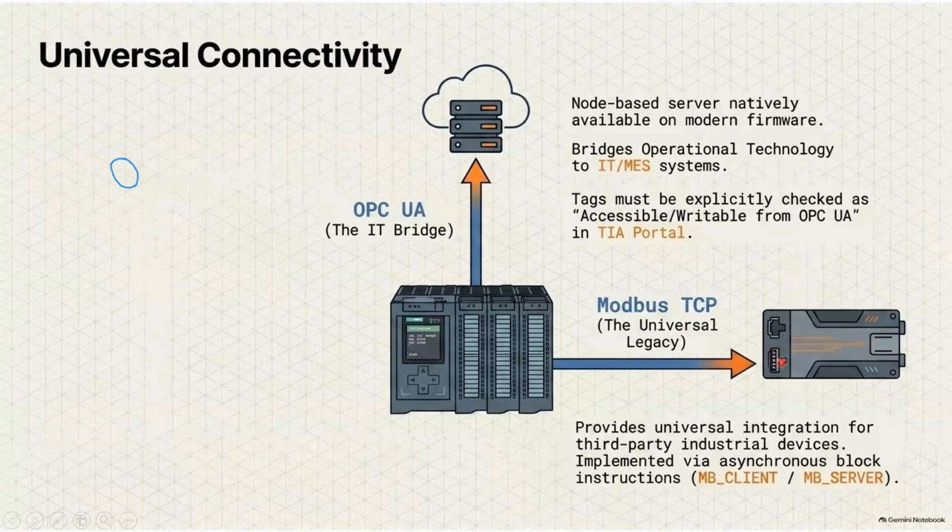The data transfer is in a huge, bulk manner. For bulk data, a single address will be defined and transferred, and the transfer rate is also very good for Profinet. With Modbus, one device's data is collected at a time, whereas Profinet is about 10 times faster than Modbus.